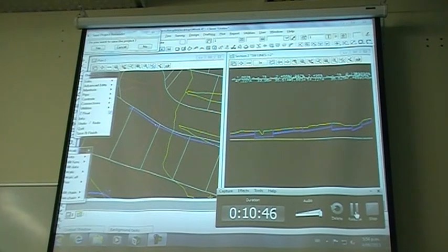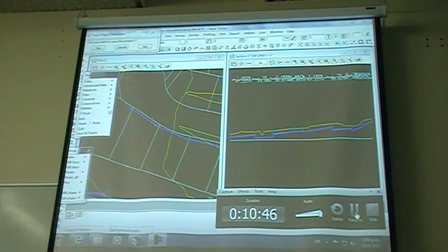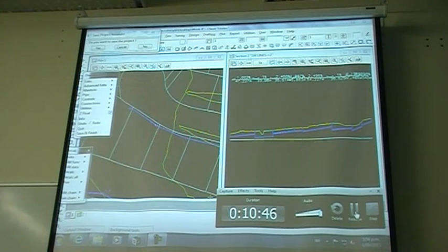That's right. So in this case, if all the low points are in that bottom left-hand corner, say I have a pipe system coming down here, I'm going to want to send a branch up this boundary and pick those up, and I'm going to want to send a branch up this boundary and pick those up. This way, I try and avoid having two lots of pipes in one person's yard.